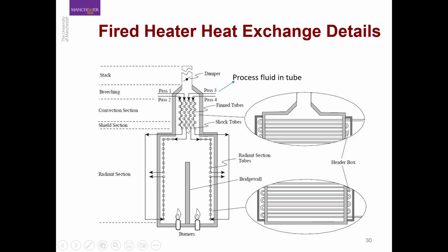Then some part of the heat gets transferred to the process fluid here again, and the flue gas gets further and further cooler, and then you finally have the convective section where the final part of the heat exchange happens, and finally the flue gas moves out of the stack.